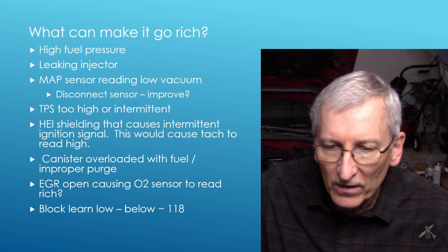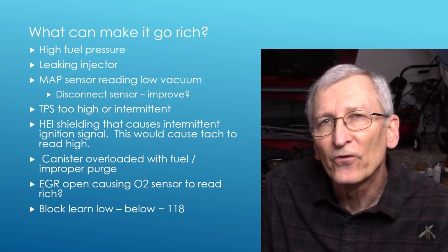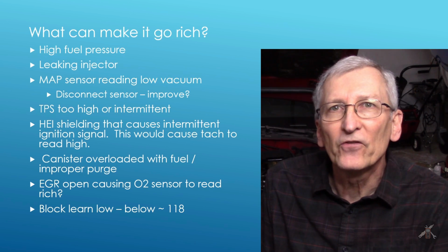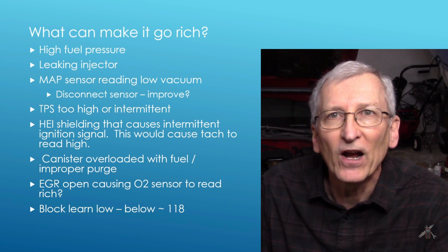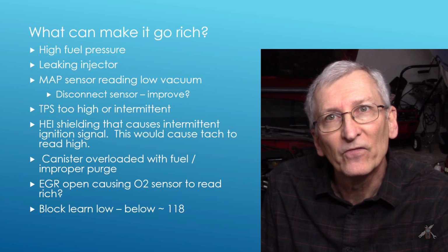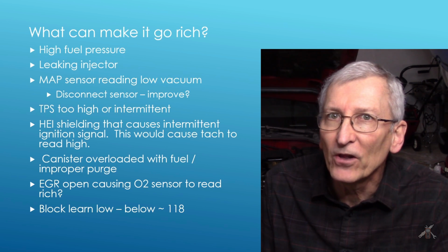EGR open, causing the oxygen sensor to read rich. See, in all of these cases, there are two things. One is, is it really rich? Or two, is your oxygen sensor just thinking it's rich? Sometimes those are hard to tell apart.